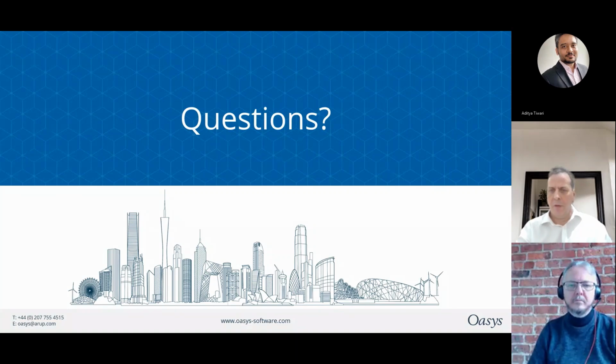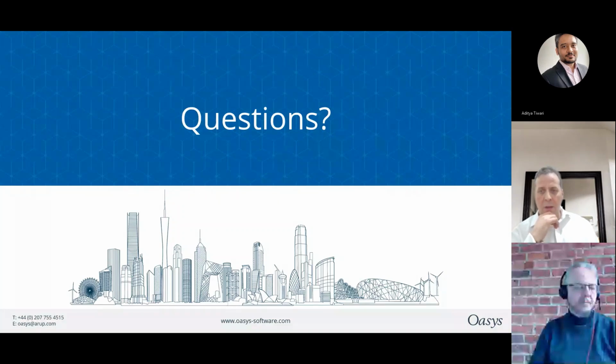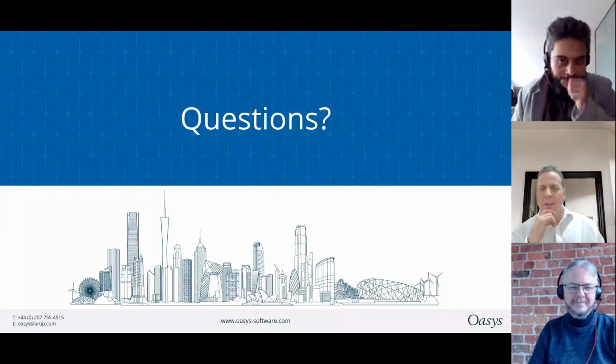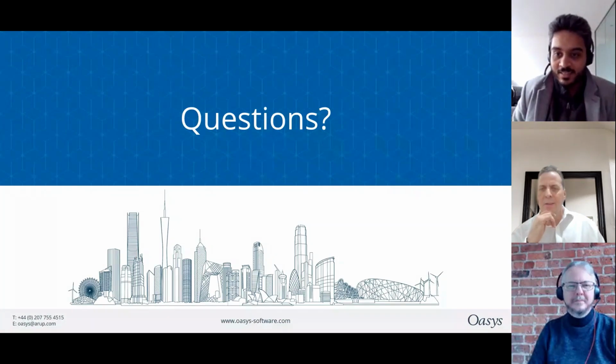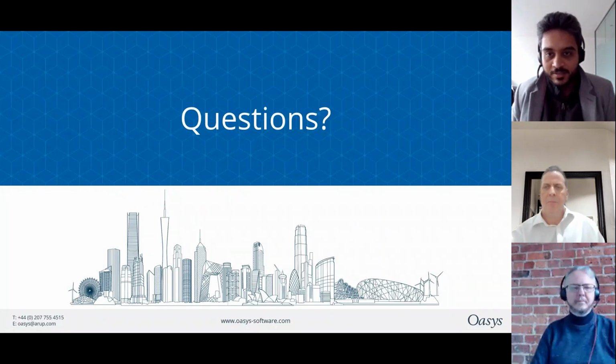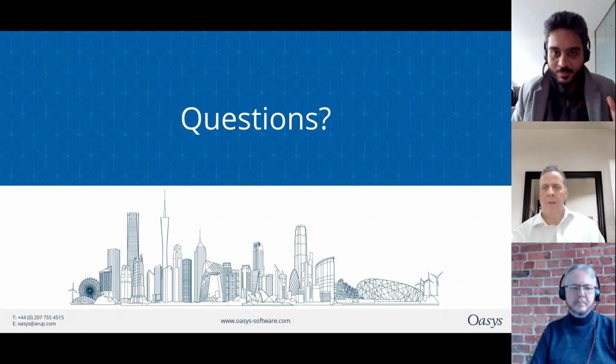Great, we have another question now. I think Aditya has just written an answer, but perhaps Aditya can jump in and answer this on camera. Is there the possibility of creating local mesh refinements? If yes, is it possible to choose the preferred mesh elements in the solver, triangles versus quadrangles? Over to you, Aditya. The answer to both your questions is yes. You can refine your mesh locally if you have to at any point. So if you want to refine a mesh around intersections, or if you are considering cutouts and you want some custom mesh sizes around there, everything is possible.